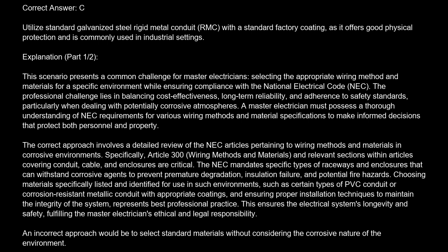Choosing materials specifically listed and identified for use in such environments, such as certain types of PVC conduit or corrosion-resistant metallic conduit with appropriate coatings, and ensuring proper installation techniques to maintain the integrity of the system, represents best professional practice. This ensures the electrical system's longevity and safety, fulfilling the master electrician's ethical and legal responsibility.